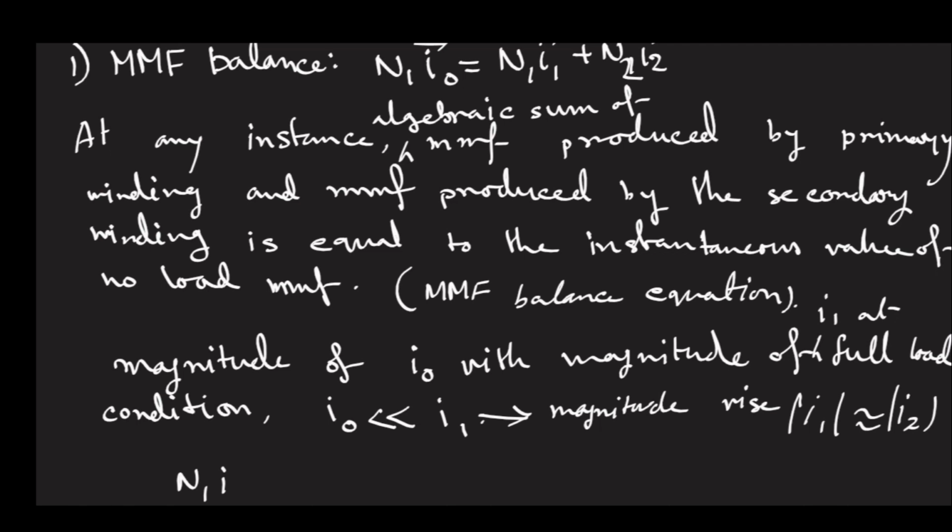that there will be, okay, from this one we can write another equation that is very important for us. If you write it equation 1, then if you perform side transposition at equation 1, then you will get I1 is equal to I naught minus I2 into N2 by N1. This instantaneous, but the same relation holds good in Phasor also.